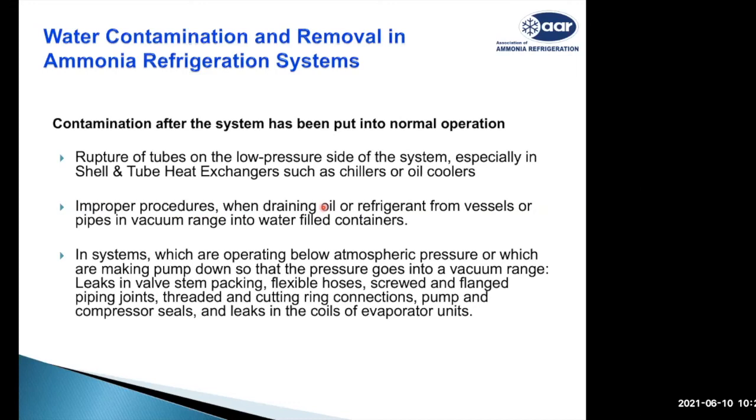Normally water accumulates at the bottom of the ammonia cylinders or ammonia plant, and ammonia is on top of it. So when you tilt the ammonia cylinder by 180 degrees, all the water in the cylinder is guaranteed to be poured into the refrigeration plant. So our water will remain in the system.